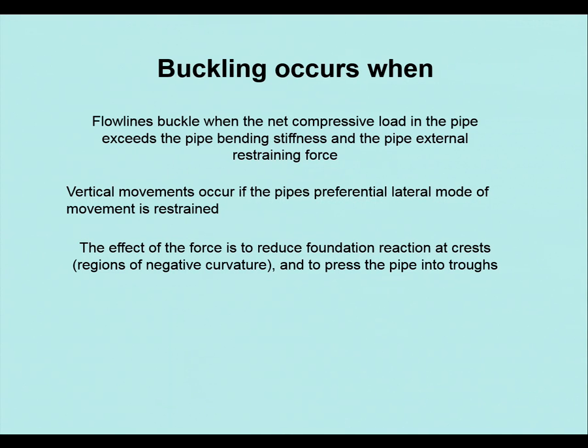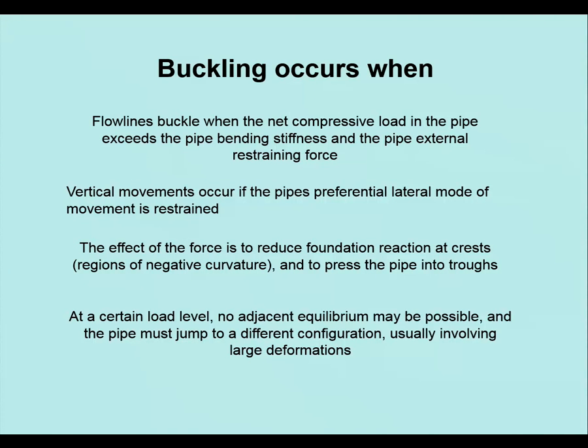If the force is to reduce, the effect of the force is to reduce foundation reaction to crest regions and can press it into the troughs as well. At certain load levels, no adjacent equilibrium may be possible, and the pipe must jump to a different configuration. So in other words, it's fully stressed up. It's really wanting to go somewhere, and if anything restraining it, if that level of restraint falls off, it'll just go. It'll snap up till it's new.